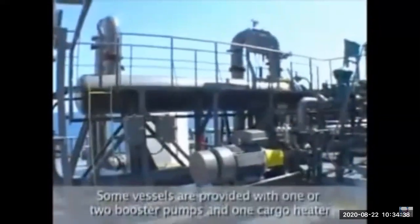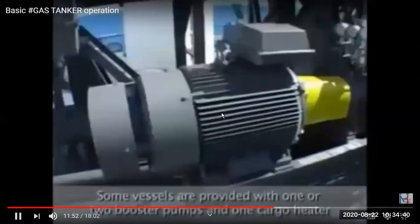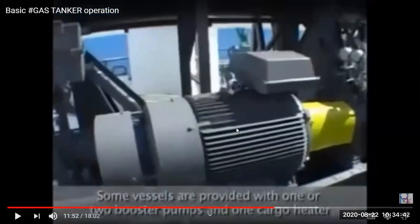Then let's see the cargo heaters and the booster pumps. A booster pump is there for boosting the pressure of the liquid. If the pump is having a lot of back pressure and is not able to discharge, then we will put in one booster pump. Sometimes you have very long pipelines, so we need more pressure of the cargo, and for that we are using a booster pump.